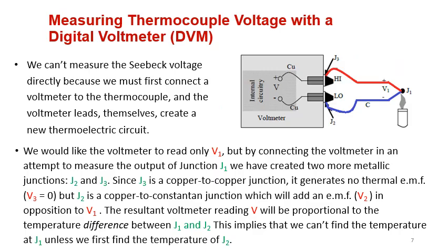Now, if I want to measure the voltage, we agreed now that the applied temperature will be converted to voltage. So here we are applying heat. The heat is converted to voltage, so the voltage between this point and this point, we want to connect it to the voltmeter. Remember that the voltmeter is having a conductor inside. So the conductor, let me take a different color, I will take this color, is having a different material.